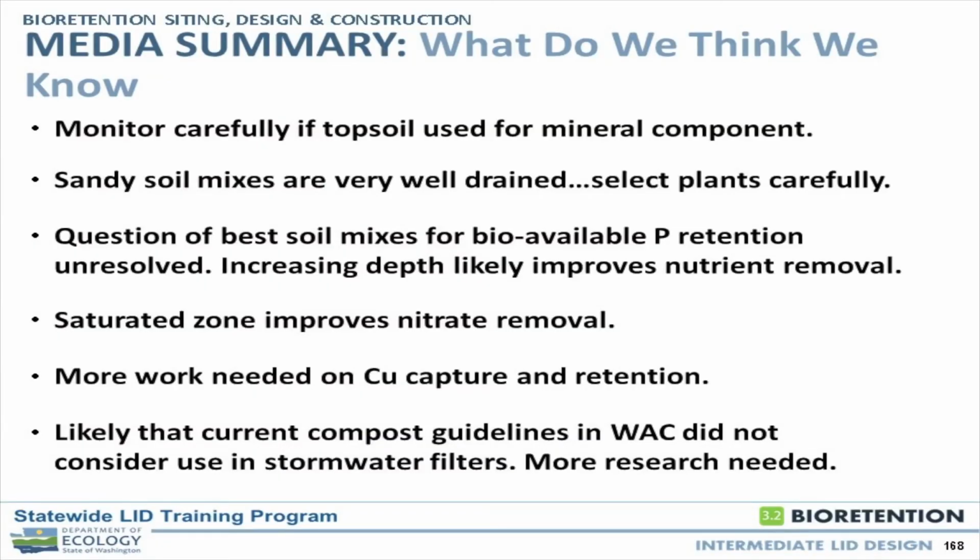Three different university programs have now confirmed that you can use a saturated zone for nitrate removal. Remember, we've talked about the flushing of nitrogen, phosphorus, and copper. For nitrogen, we found that you can successfully remove nitrate by using a saturated zone. How do you create a saturated zone in the bottom of a bioretention area? An elevated underdrain, and there are a number of different designs, and we talked about some of those. You simply create an elevated underdrain, so you have a saturated zone underneath. That saturated zone promotes bacteria to use the nitrogen for the respiration process. So it converts nitrate to nitrogen gas.